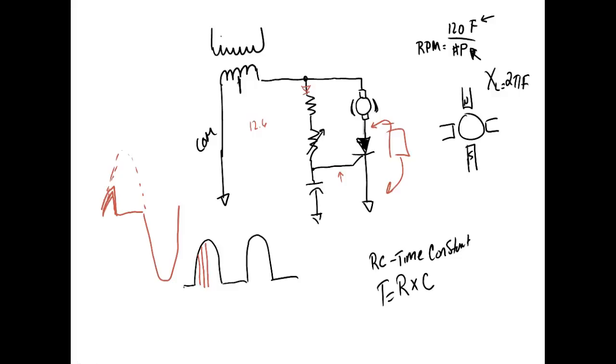So what I'm saying, if you're dealing with a high enough voltage, once you come through all this stuff, if this voltage right here is high enough to break that thing over into reverse voltage, then you'd come in and you'd just put a diode right there. So what it would do is it would let the positive come through, but when this right here went negative, it would block it. Right? Very simple circuit. Okay, y'all go ahead and sit down. We'll look at some firing circuits to let you see how complicated they are.